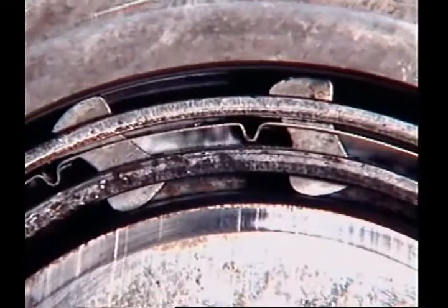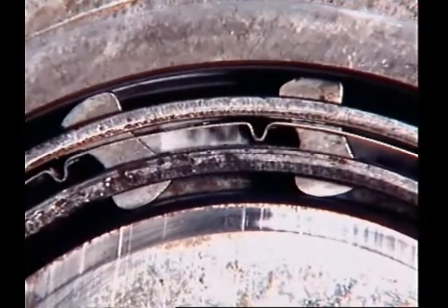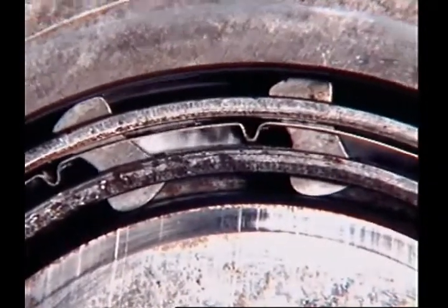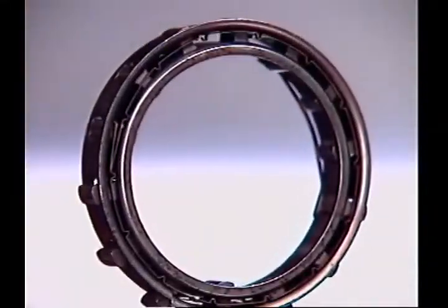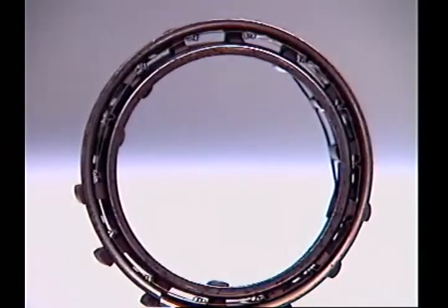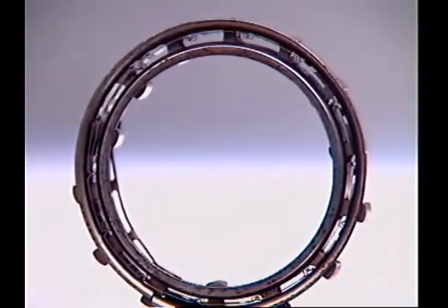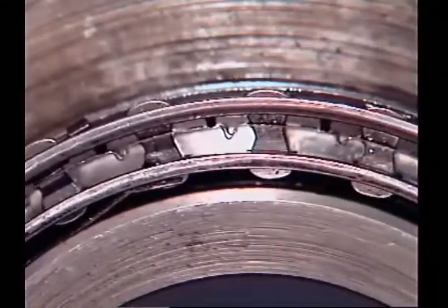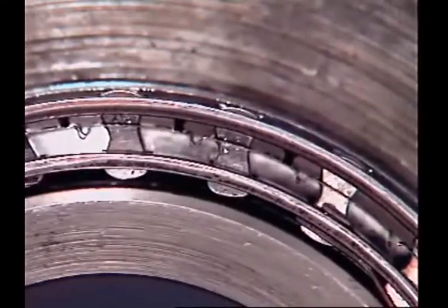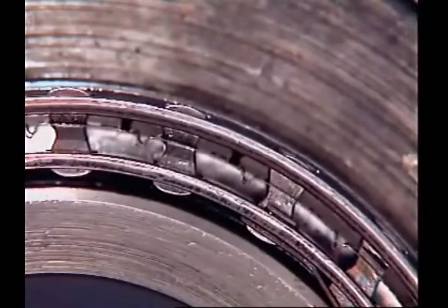Equally spaced sprags between the two races produce a wedging action to stop the stator rotating in reverse. The sprags are held in place by a spring-loaded cage. The cage moves the sprags together so that when the stator is locked, each carries an equal share of the load.